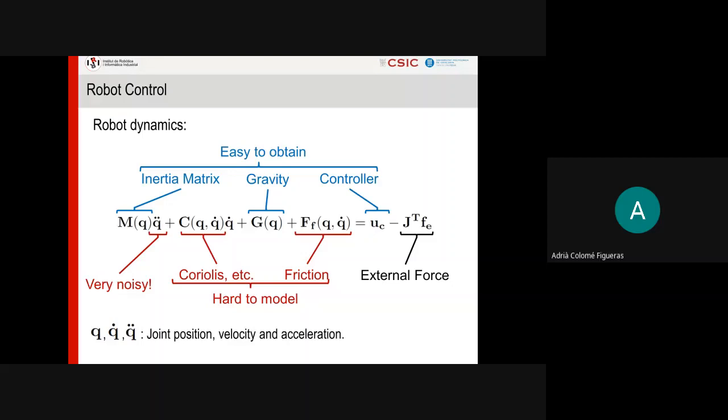And why is that? Some robots, not all, have accelerometers or direct velocity readings. Some robots only have position encoders. In such situations, you have to be very careful, because if you extract an acceleration from there, you will be differentiating the position twice. Imagine that you have a time step of 1 millisecond. If you differentiate the position, the error on the position encoder will be multiplied by 1000. But if you differentiate again, this error will be multiplied by 1 million.